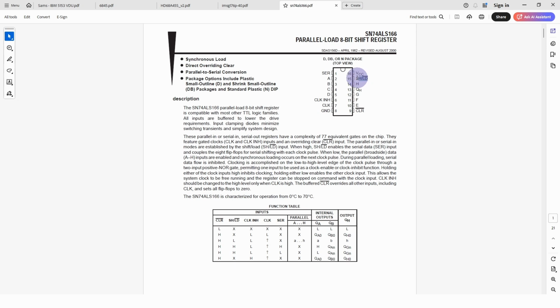So when that goes low, then it loads the pixel data from the character ROM in there. And then the clock, which is driven by the dot clock, shifts the input out through the QH output. And so that's effectively the output of the pixel data to feed into foreground, background logic.